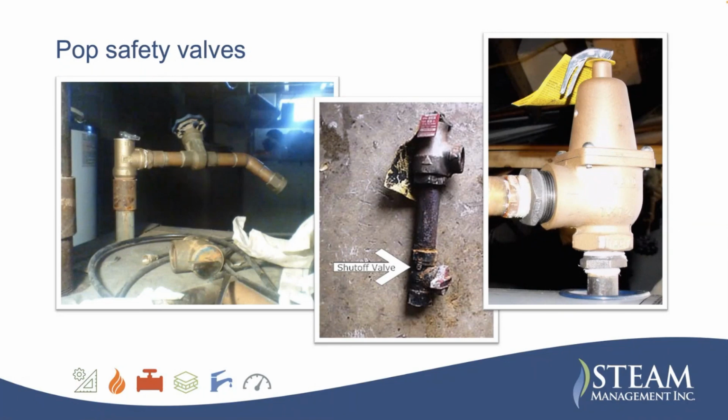So when I asked the installer, I said, "Hey, you reduced that." He said, "Well, I didn't have any 2-inch, but I had all kinds of 3/4 inch." And that's how he rationalized it to himself. If you see this on a job site, this has to be removed and replaced with the same pipe diameter or even bigger.